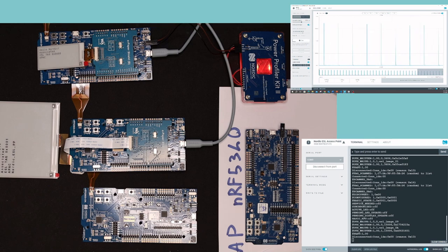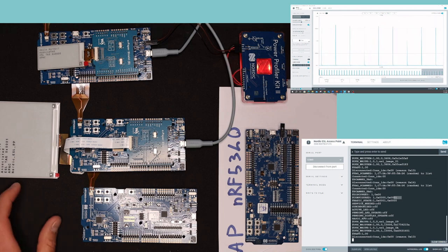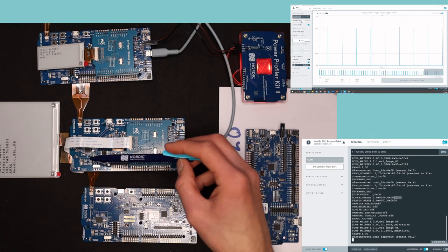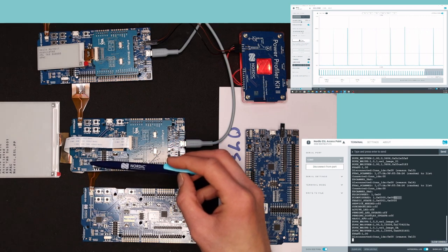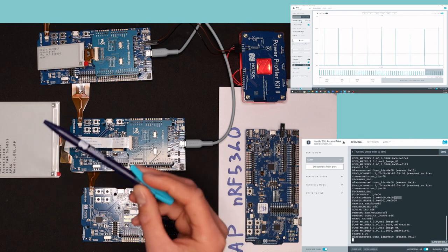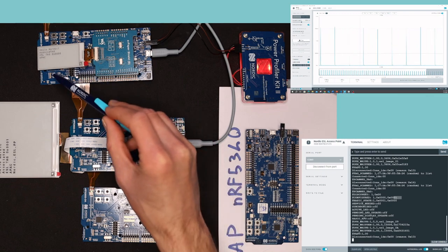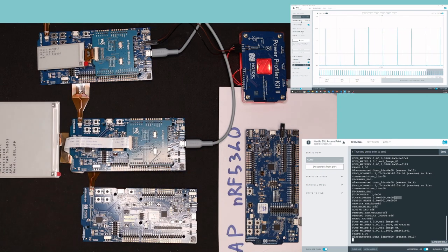Also in this case, the tag has been assigned by the access point to group 0. We can see it here, and the ESL ID address is 01. So this is the second tag we have in the same group. You can see also in the display we have this information. The tag is associated, and we have the ESL address here. You can see on LED 4, it's blinking slowly and indicating this is synchronized. In this case, we don't have the LED because we are performing power measurement, and so we have removed for a second the LED light here.